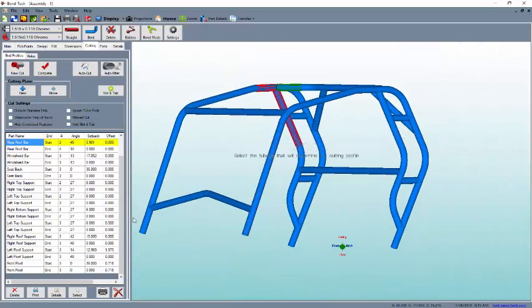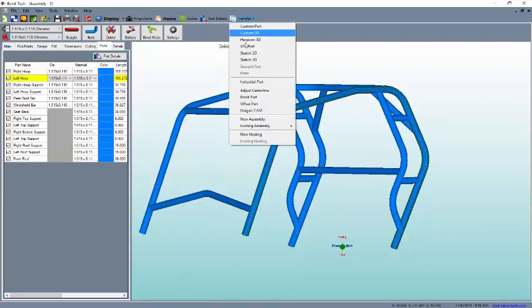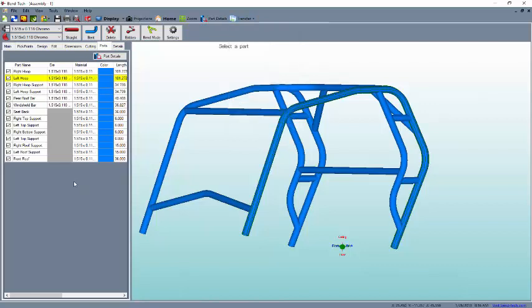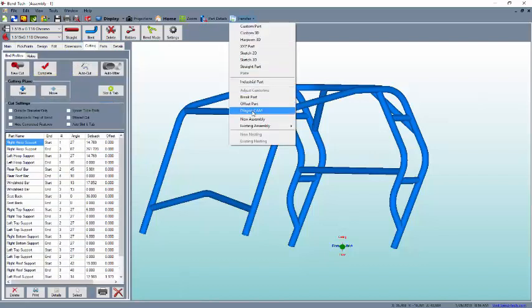And then afterwards, the parts are available in the assembly interface. They're available from this parts tab. You can either select them individually and send them out to the Dragon Cam software to get them in flat layout and send them to the Dragon. Or if you're in any other tab other than the parts tab, say if I'm in the cutting tab and I transfer to Dragon Cam, it will send the entire project. So let's try that real quick right now.